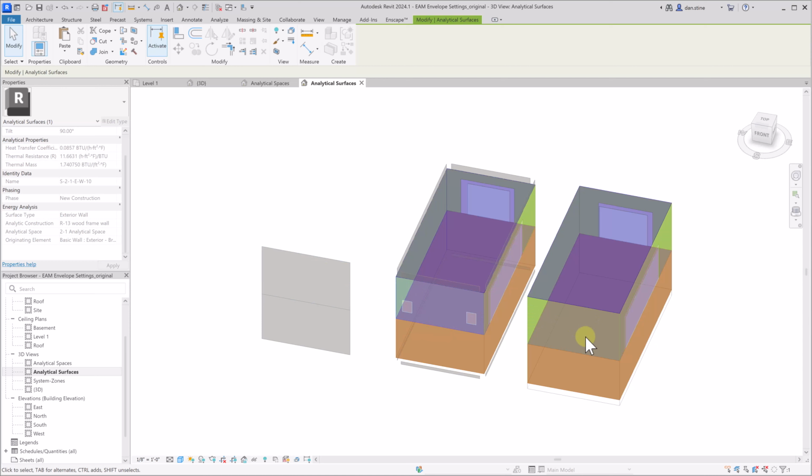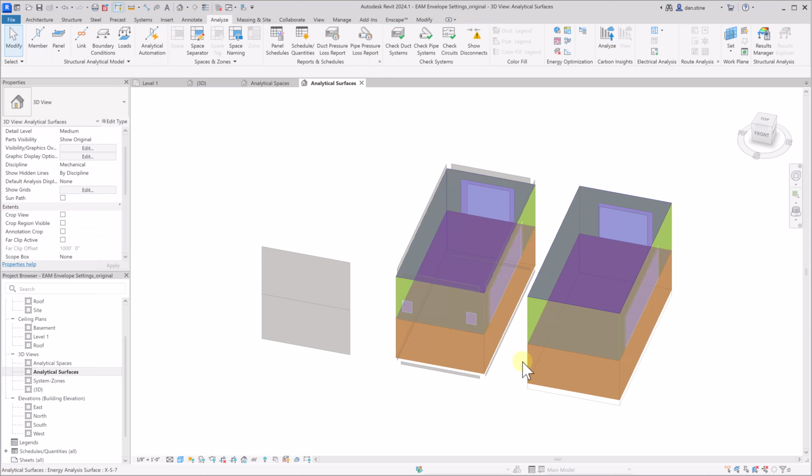an exterior wall. For the building itself, by the way, I don't have any Revit room or space elements placed. Revit's voxel algorithm that's used to create the energy analysis model automatically determines what's an exterior wall, what's a slab on grade, what's an interior floor, what's a below grade floor. And to that point then, we'll look at this a little further.